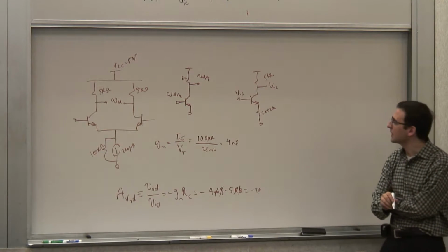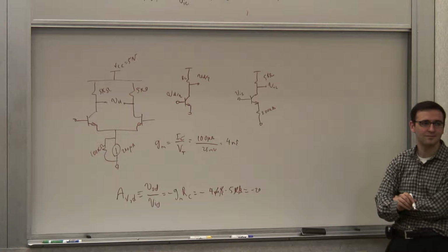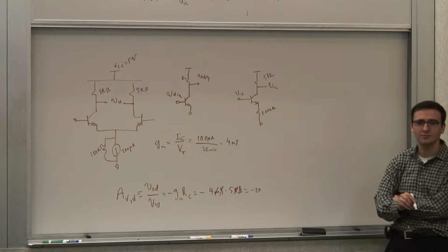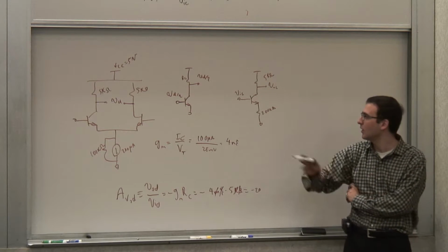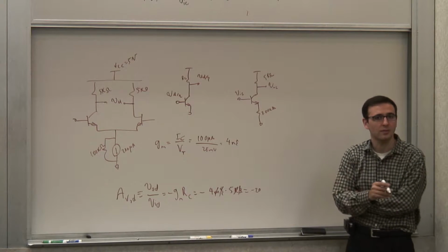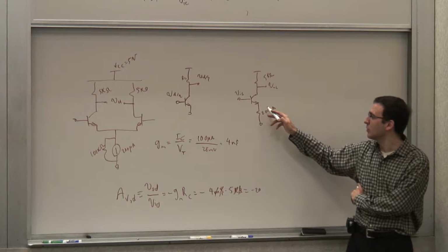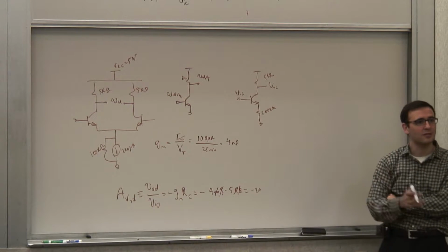So what is the gain of this thing? Ballpark. Or 1/40. 1/40, right? It's the ratio of that resistor to this resistor, because rπ is relatively small compared to that. If you want to take it into account, 200 kilo ohms plus 250 ohms, you can calculate it.